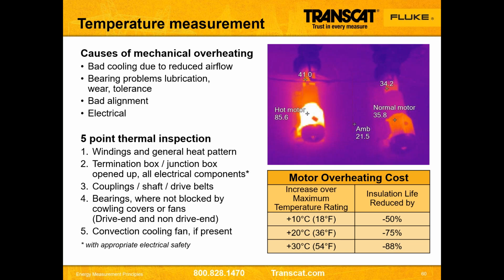And as you can see, for every 10 degrees Celsius rise beyond that, the life of that device drops dramatically, doesn't it? So it'll overheat, and insulation will fail, and it can fault any one of the 3 phases together and any phase to ground. So I really have 6 fault paths on a motor. If it gets hot enough, the insulation gets brittle, it cracks, and it faults, and it dies.